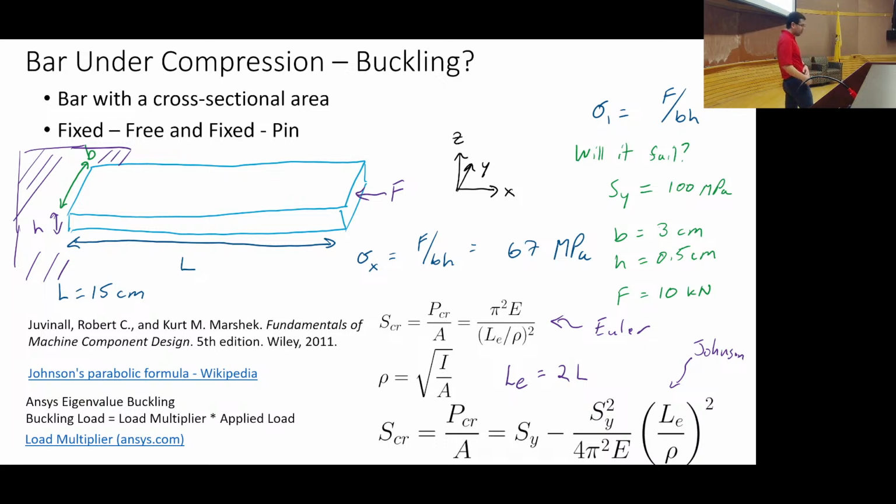But if this is my leg, and I think of all my tendons and everything as strings, and I'm in some type of tensile testing machine that's pulling me apart, it's not going to buckle. It's just going to be pulling. In that case, failure is going to be due to the strength of the materials involved. In the buckling case, you might have a very strong material, but because of the geometry, you have buckling.